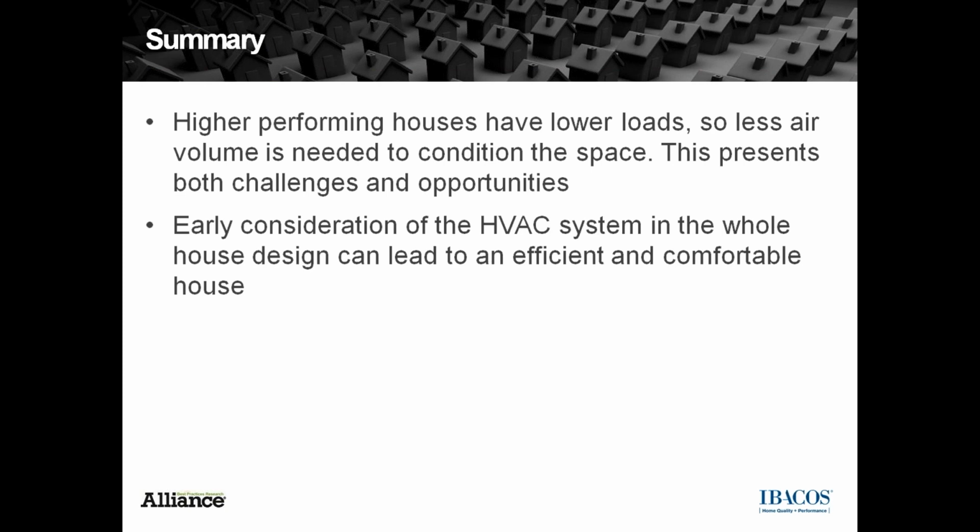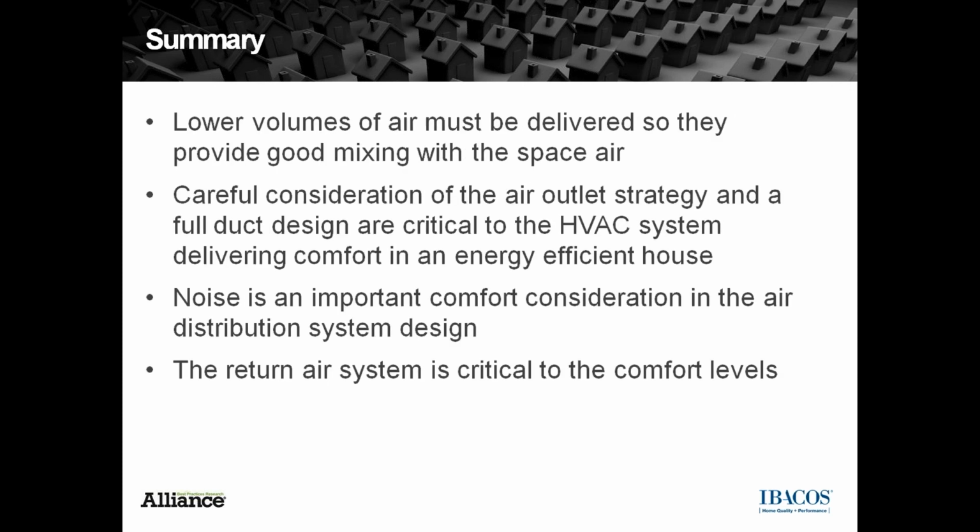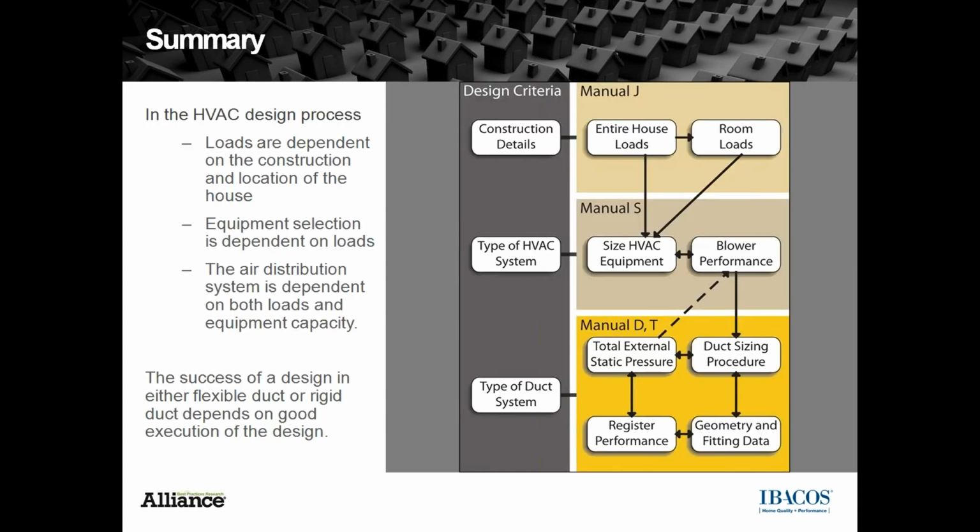We discussed that the higher performing houses do have lower loads, so less air is going to be required to condition them. And early consideration of the HVAC system in the whole house design will help you both in performance and cost. Lower volumes of air must be mixed properly to get that conditioning, so your outlet selection is very important there. Noise must be considered just as much as temperature and draft, and the return air system is critical to the performance of the system.